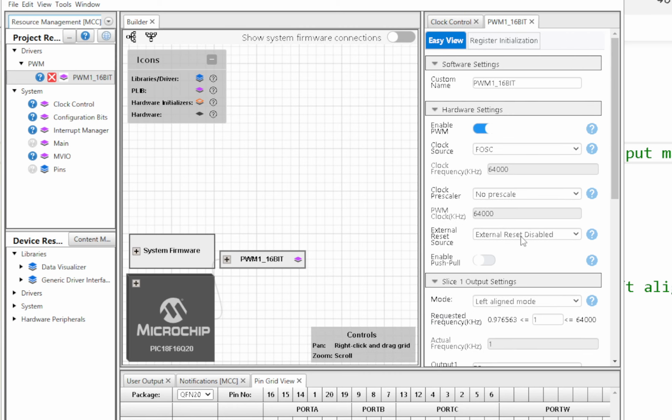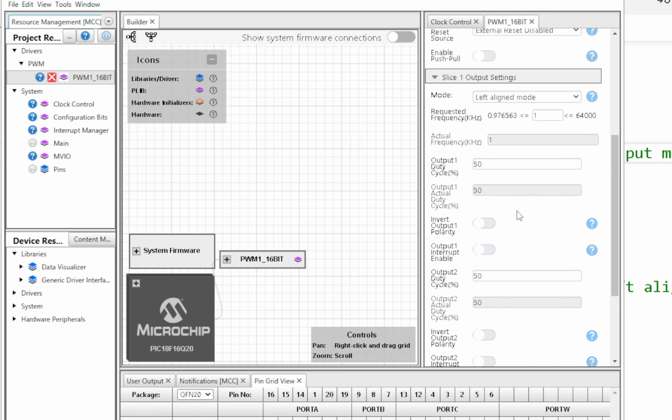and let's have a look what we're going to set. Leave the top, that's fine. And we're going to come into here, and actual frequency in kilohertz is 38. Oh, I'll do it in this window here, even better, look, 38. The range in here is 0.97 kilohertz to 64,000 kilohertz. Pretty impressive stuff. And the output is going to be 50, which is great. Now, I already said that in each module here, you can have 2 of these things. So just because I want to prove something to you, just put 100% in the bottom one. You might not use it, for instance. You might turn it off.